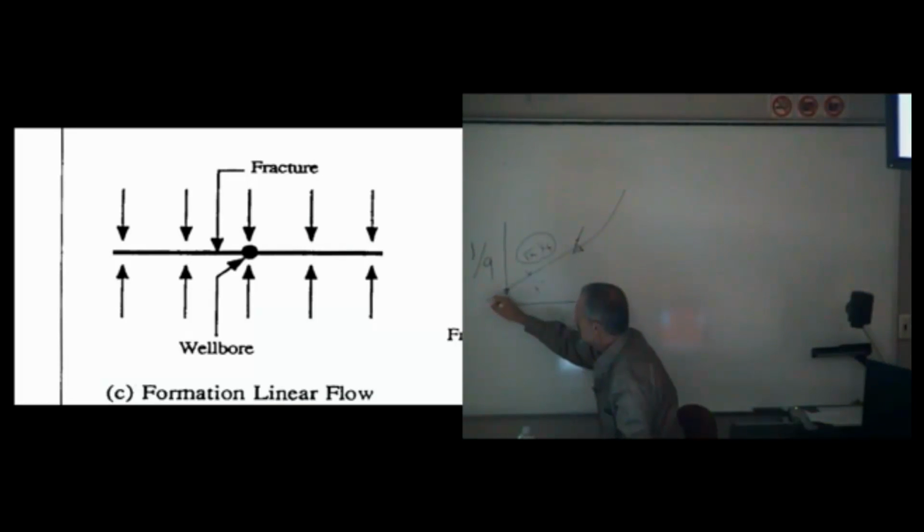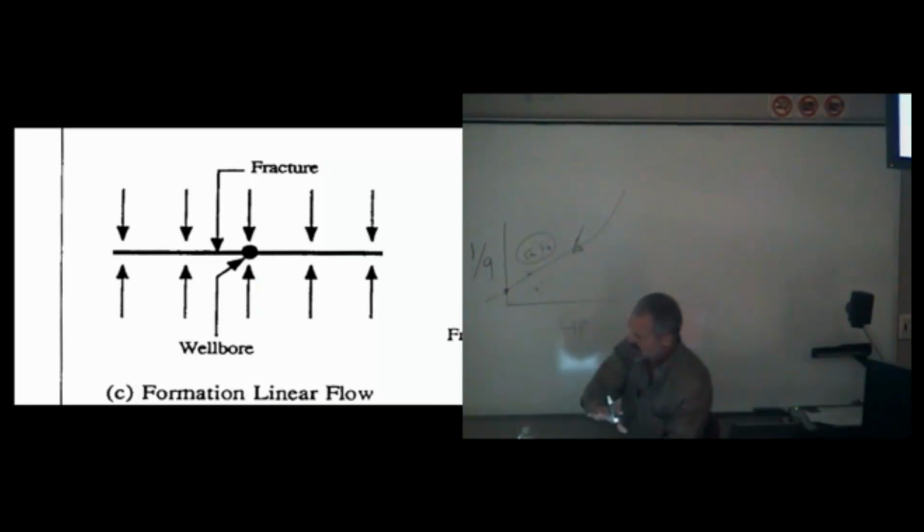And lastly, this intercept, both conceptually and calculatably, gives me my frac conductivity. So if you're a completion engineer, the most important thing to you is the intercept, because you're trying to improve frac conductivity. So you can measure your frac conductivity from pressure buildup analysis or transient rate analysis and figure out what jobs gave you what conductivity and try to optimize your frac conductivity.